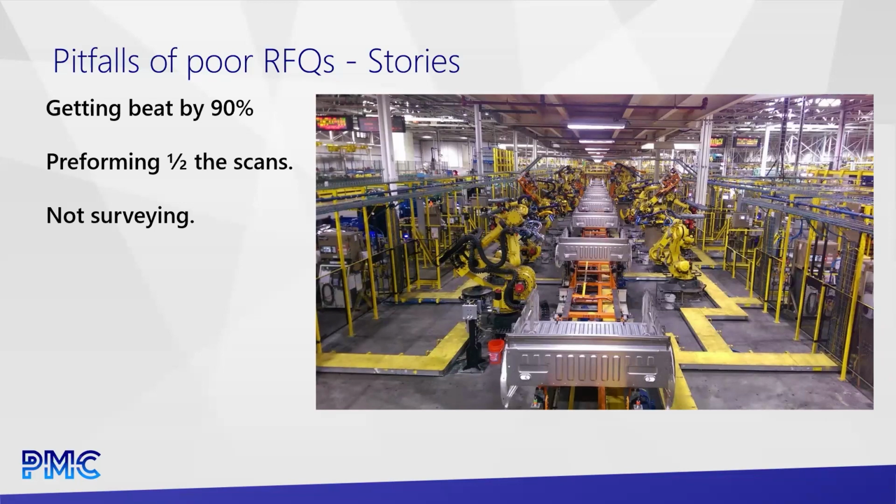And what we've seen are things like a point cloud looks good and you start working on it over on maybe the east side of the factory. And then as the modelers are working through towards the west side, they start noticing things like building columns are starting to drift wider and wider. What maybe should have been 50 foot between building columns, by the time you get to the far end of the factory, they're coming in at 53 and 54 foot column to column, even though in real life they're 50, because that data is separating and pulling apart by that much.